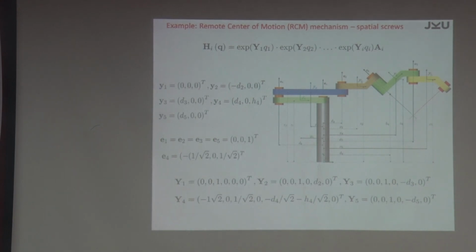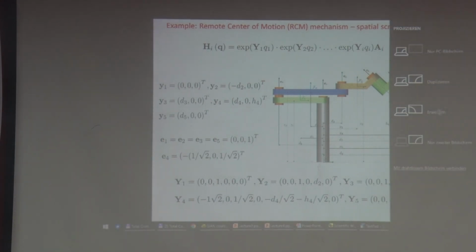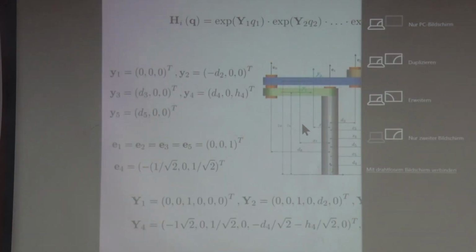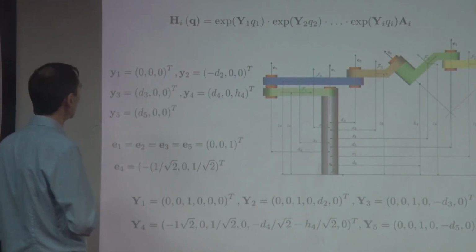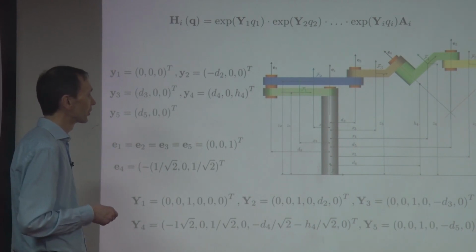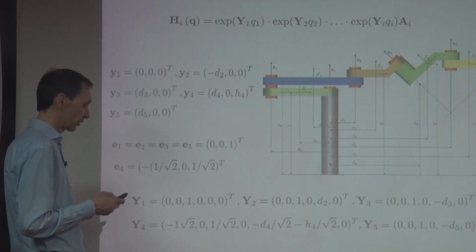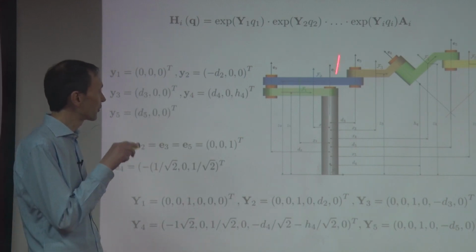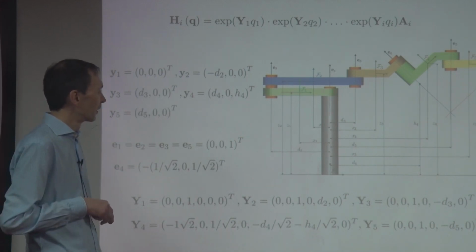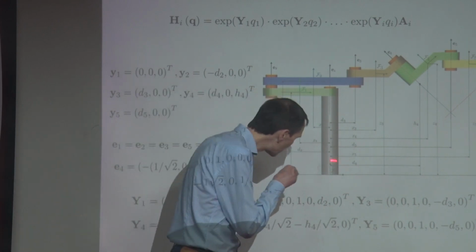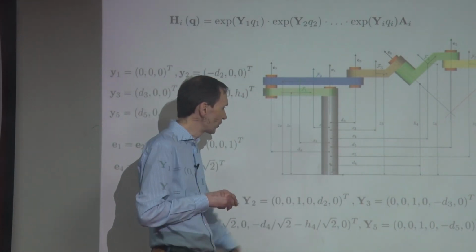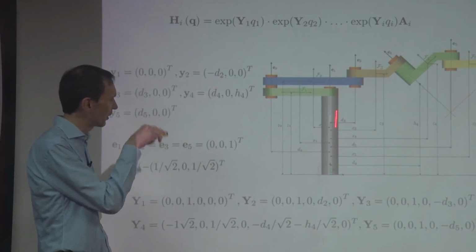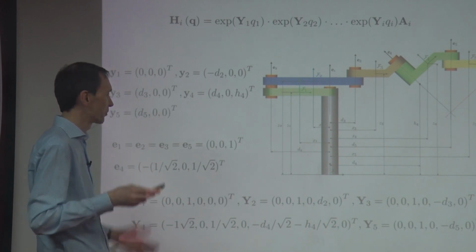Make it a bit bigger, I guess. Makes sense. Okay. What do you need? Let's start with the unit vectors. So you need the unit vectors to all these joint axes here. And the space fixed frame is a bit small here, but the green one is here. I just placed it at the axis of the first joint, but it could be anywhere.